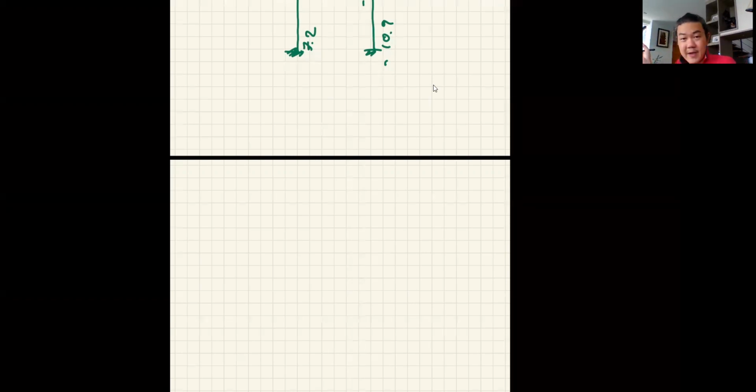Now, generally speaking, if you mess up the analysis for whatever reasons, unless it is fatal, like if it's a fixed support and you analyze it as a hinge, that is absolutely unacceptable. But let's say if you mess up here, there, everywhere, the error would not be so large. Now, when the structure gets complicated, and we all know that it takes time to analyze, in comes another very useful thing that you need to know. It's what we call approximation analysis.